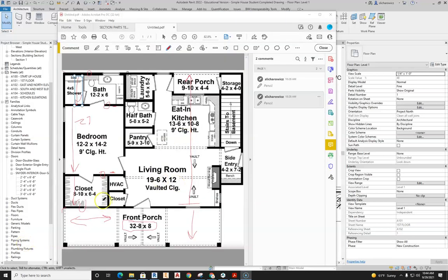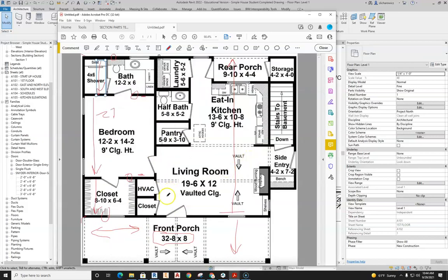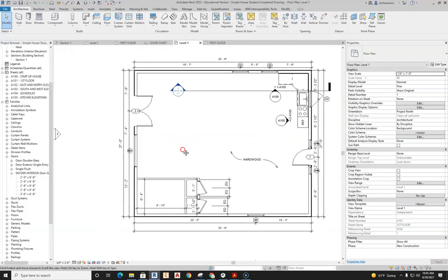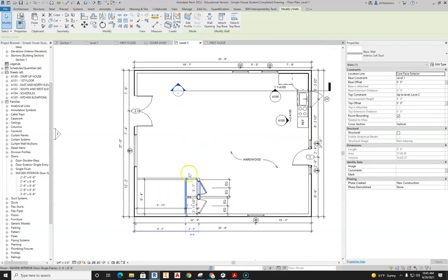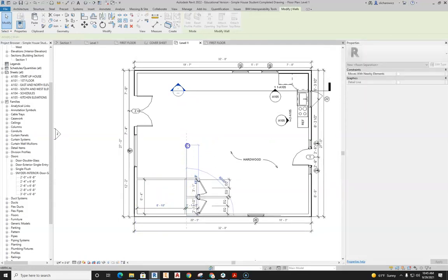As you go back and start looking at a drawing or a design, you want things to line up. You don't want kind of funky jogs and things like that in your drawing. Okay? This wall goes all the way through this house, straight through, which is good. You want nice straight walls when you need to do construction and build, so it goes all the way through. What I'll do back here in Revit is because I have this wall designed and put in the right spot, I'm just going to click on this wall and drag it all the way across the house.